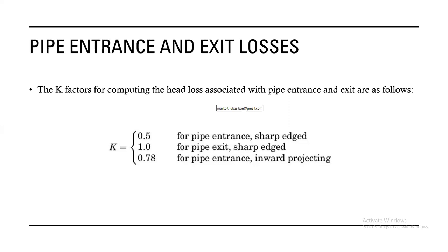They just put the pumps haphazardly without studying or calculating their system resistance, and then it results in pumps which are undersized. Then you have many breakdowns of pumps which are oversized, and also you find that you're using too much energy. But as we go on with the presentations, I'll get to the point where we are sizing the pumps using all this knowledge we've been trying to accumulate so far.